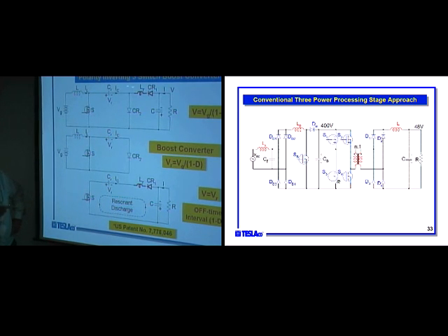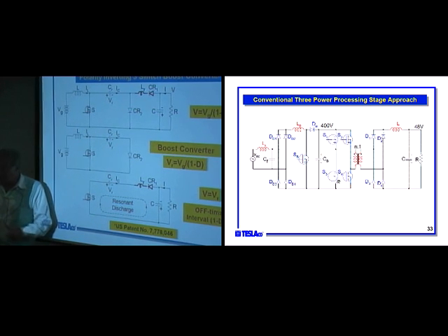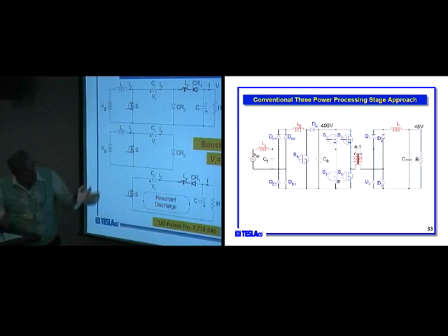And then this part here acts like a translation stage. This is like a resonant inductor, and this capacitor transfers its DC charge to the DC charge here. So what's resonating here is only the ripple on a capacitor. And that's why this resonant inductor is very small. Okay? So basically, that permits this converter to be operated in the same way as a regular boost converter, but it provides negative output voltage polarity.